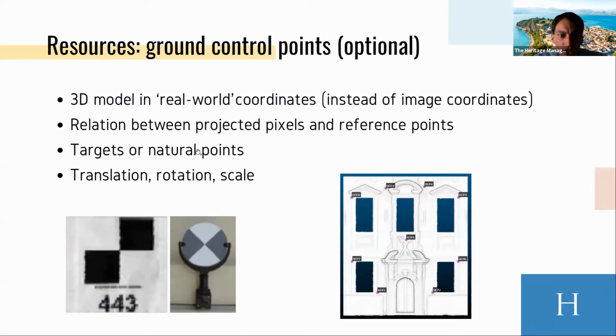We will start in a more difficult fashion, being natural points. So the exercise that we will do is actually covering a facade somewhere in Ghent. And on this facade, I have selected 9 ground control points that are more or less easy to trace using difference in texture. So we will see how that works. They're actually natural points that you can use.